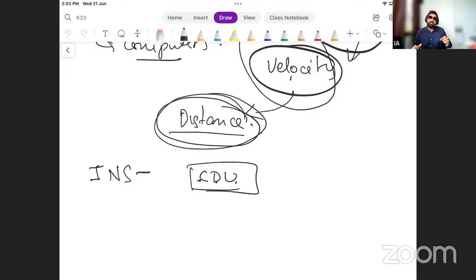Such information is widely used in all our wide body and glass cockpit aircraft. So the things that you see in videos where pilots are seen inputting some data on some computer screen, they are feeding in the present position for the INS system. And then they're also feeding in waypoints, which is an advanced function. If you can feed in the waypoint lat longs, and the destination and the departure, then the INS itself will determine whether the aircraft has gone off track.